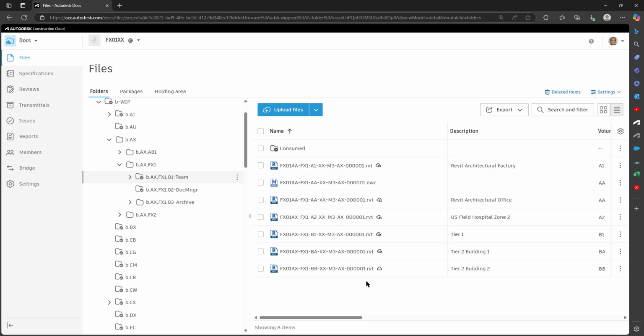The difference between a cloud file and a normal Revit file is that cloud files resolve the first part of the file path when they are linked, because we can link them in as cloud references, firstly, and secondly, they avail themselves to being updated year by year.